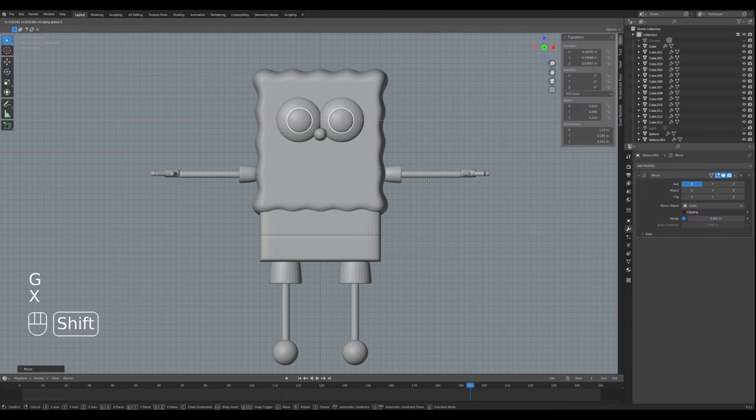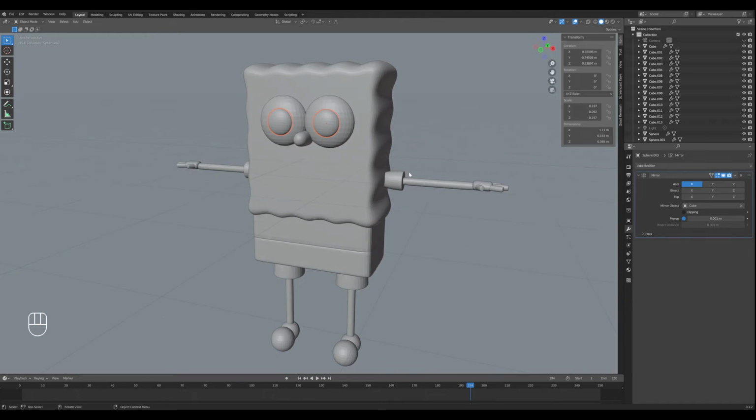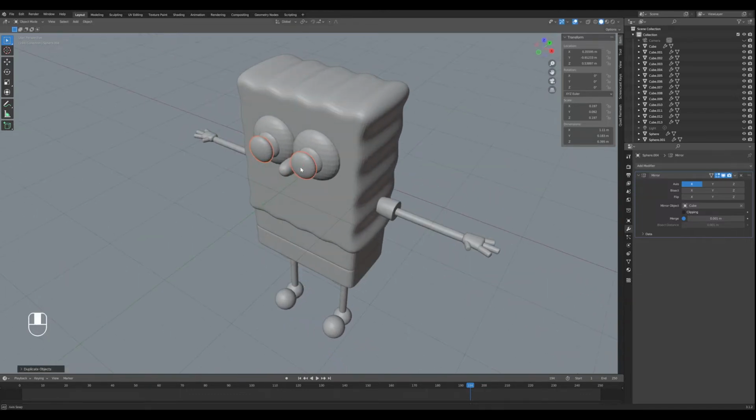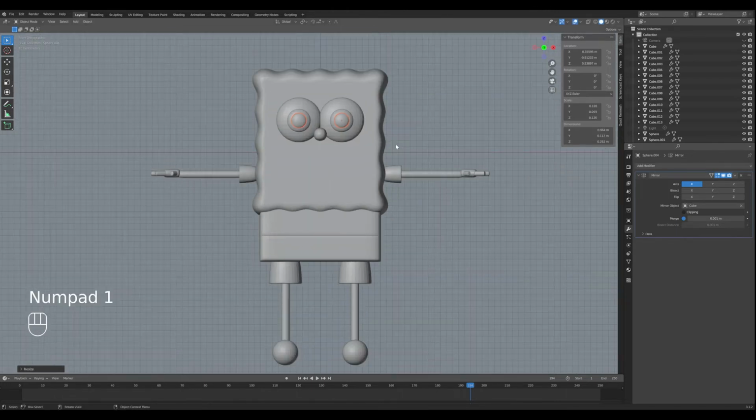And what do we think? I'm gonna move them along the x-axis like this. It's kind of got owl eyes, right? And then let's see, proportionally, those look a little big, so I'm gonna scale down. Okay, now we need the pupils of his eye, right? So with those selected, I'm gonna Shift D to duplicate, and then GY to move them out. See that extra layer? I'm already gonna scale down, so I'm gonna do that before I move into the front view. Like so.